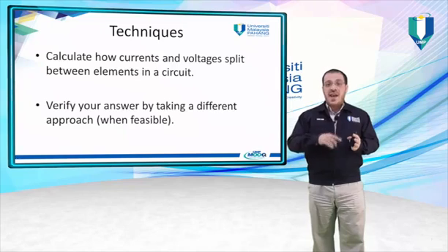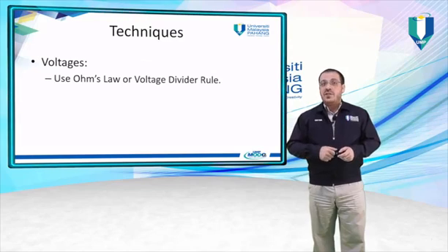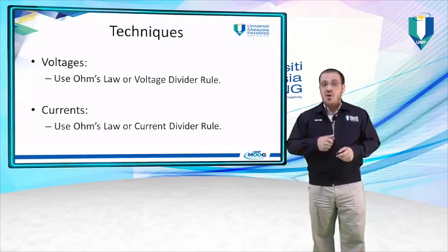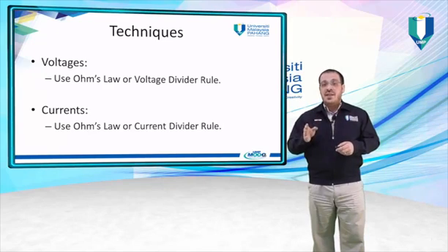If it's possible to solve the same problem another way, do it to make sure your calculation is correct. And always remember, for voltage, use Ohm's law or the voltage divider rule. For currents, use Ohm's law or the current divider rule. Series-parallel is a combination of series and parallel, so all the rules are applicable. As I said previously, current is always the same in series and voltage is always the same in parallel. Then we can use Ohm's law and the voltage divider for voltage, and the current divider for current.